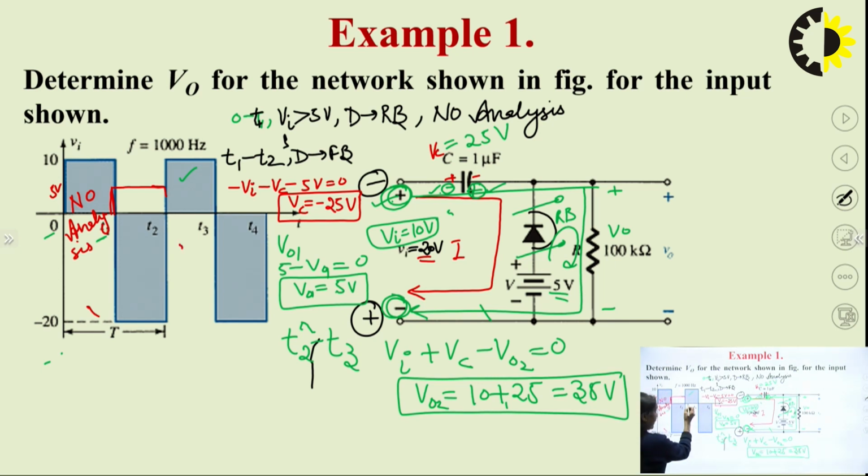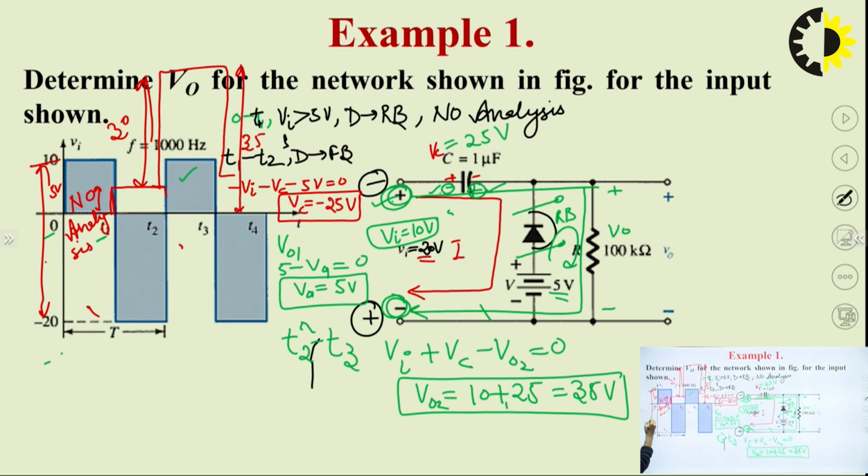So I'll measure again from this place. So this is 35, this is 5. So how much will this be? 30 volts. And you can see this is also 30 volts.